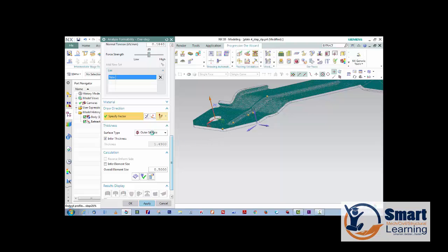Basically the outer surface is there. So you can just go to the inner surface and give the thickness. You have to see which surface you extracted, outer or inner. That is the only point, and it is not a major thing. Mid planes: so 3 options are there. I am ignoring that and going for the report. Springback computation is started.